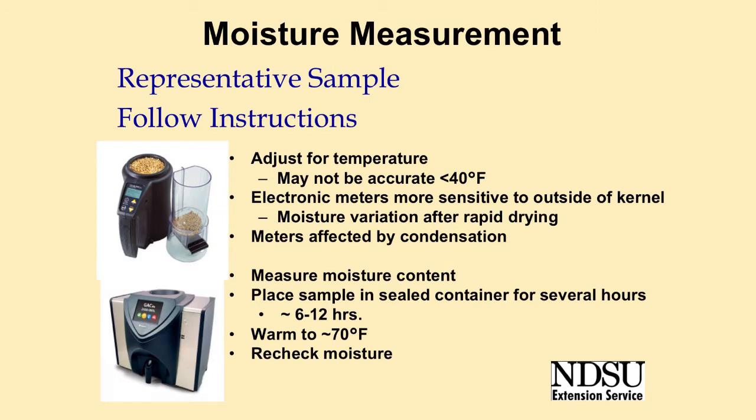The accuracy of a moisture measurement depends on many factors. The barley in the moisture meter is a small quantity. Is it representative of the grain in the various parts of the field? There is also variability in a truck, with grain separating based on size and density. Moisture meters are affected by grain temperature. Make sure the meter reading adjusts for temperature and that the grain is within the meter's operating range.